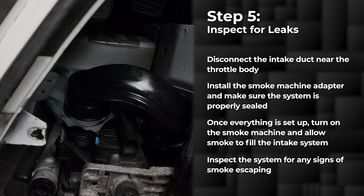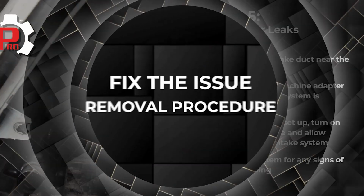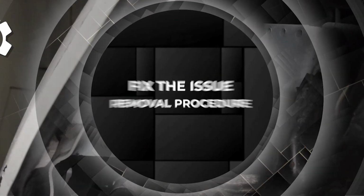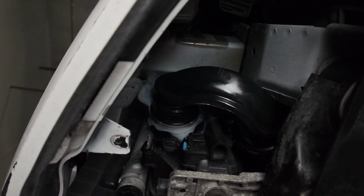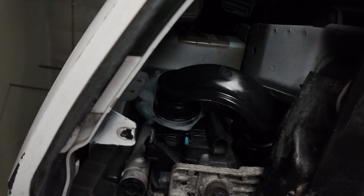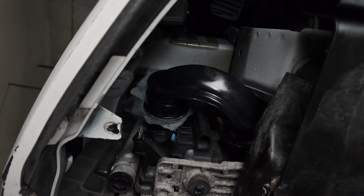Here we found that the intercooler is leaking. You can see smoke from there. We've confirmed that the intercooler hoses are leaking, so we're going to replace them. Follow these step-by-step instructions and remember to wear the appropriate PPE throughout the procedure.